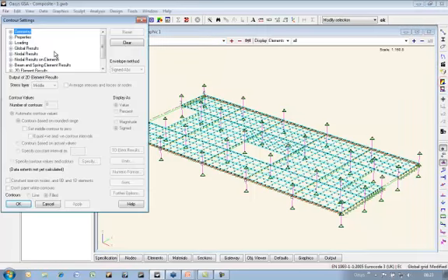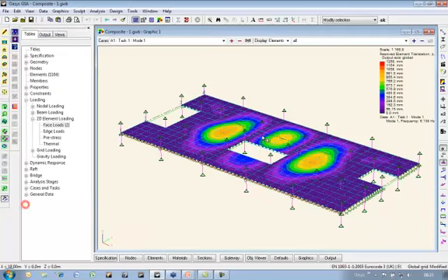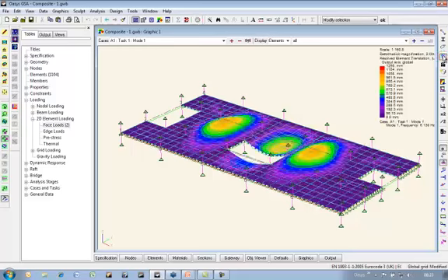And let's look at the shape, and there's our first mode, coming in at 6 Hz. So this is a low frequency floor. Walking speed is generally up to about 2.5 Hz. A high frequency floor starts at 4.5 times the walking frequency, so 10-12 Hz and above. So this is good. What we need to do now is find all the modes up to 15 Hz.